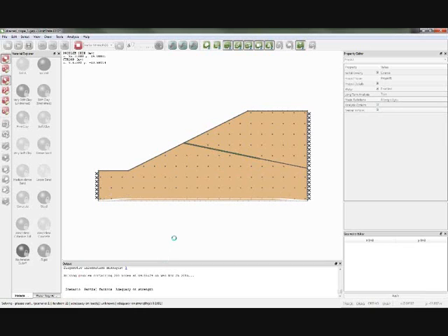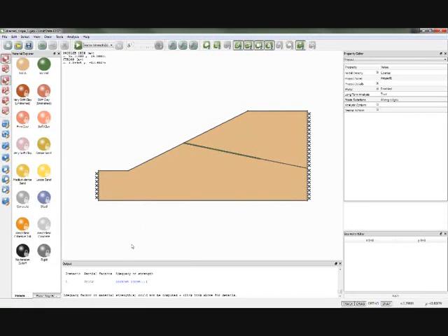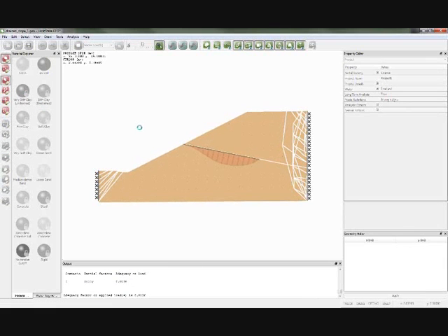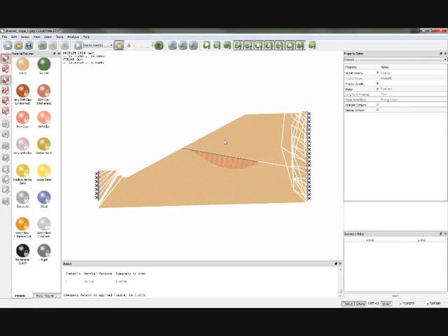Going to get there eventually. It's a kind of unusual problem to throw at it. Yeah, didn't like that one. What I can do is change to what we call a factor load mode, and we've got true on there. Basically what we're asking the software is how much heavier does this soil have to be to cause collapse, and basically it's just falling into that void.